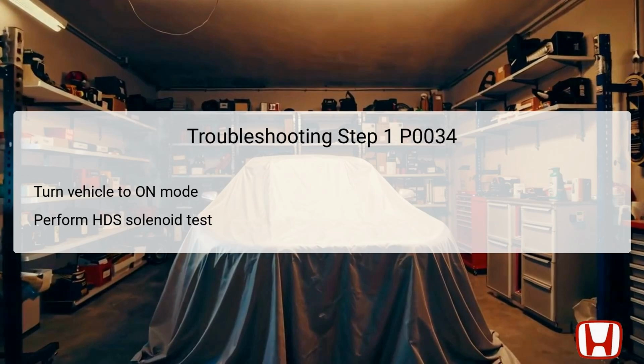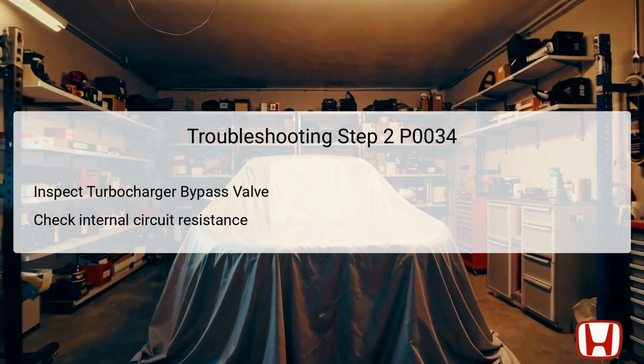The HDS reads real-time data from the PCM, enabling you to verify if the control mechanisms are functioning correctly. A successful test will show a response from the solenoid, confirming its operational integrity. Should the test reveal no proper functioning, further inspections are warranted to locate the root of the issue, guiding the technician in deciding what components require attention next.